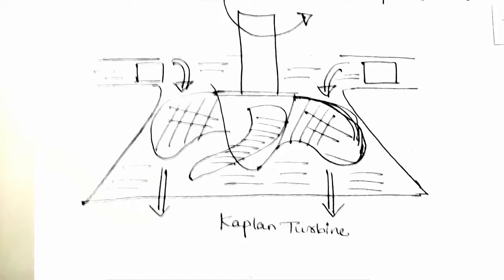So when the velocity of the water is large, it is possible to use a Pelton wheel turbine, and if there's a large quantity of water but the velocity is less, in such an arrangement where the head is lower, like 80 meter head or 80 to 100 meter head, in such cases Francis turbines are used, since the water will be available in large quantity.